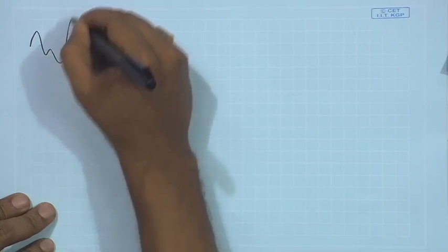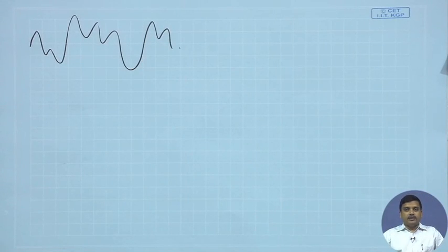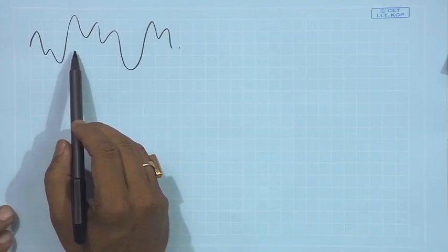If I say that we have a particular signal, let's say I have this signal. What comes to your mind is through Fourier analysis you can break it down, and you can find the components of frequencies which build this signal. So there will be, let's say, a whole set of sinusoids, a huge number depending upon the bandwidth you restrict your system to, and you find a coefficient for each sinusoid. So when you add them up with appropriate phase and amplitude, you can regenerate this particular signal.